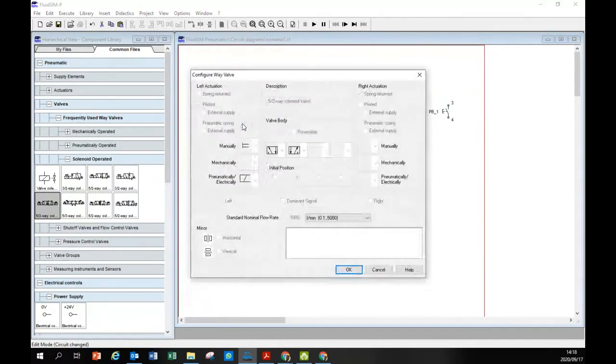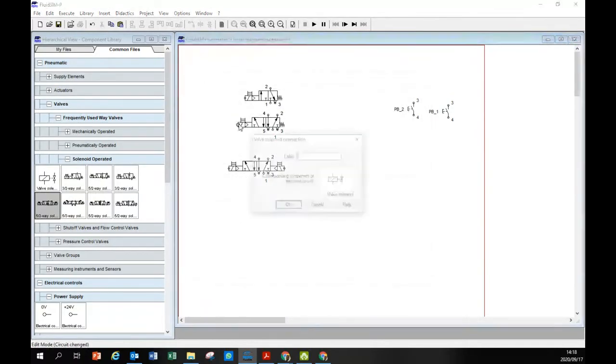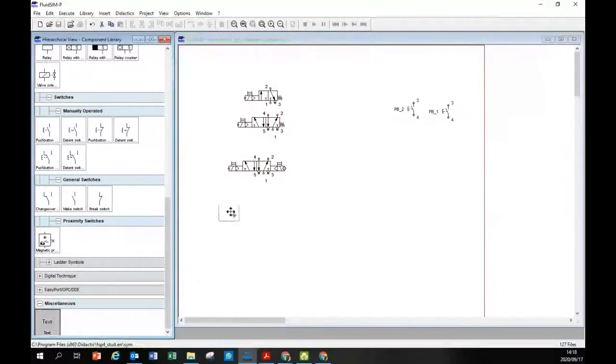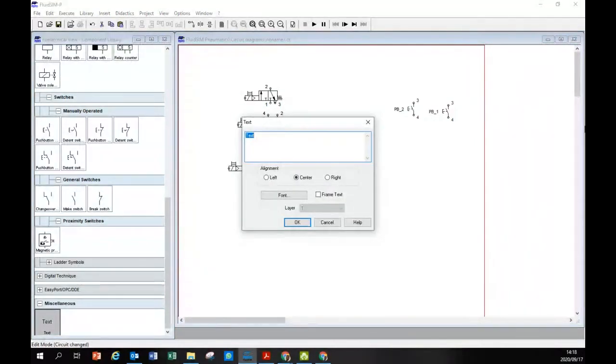We actuate it there. That's right, because you can label once. Can you label this side? You can't. You can label once this side. Can you label the other side? You can't. This one, you can label on both sides. That's why it's a double pilot. Double pilot. Obviously, solenoid. Okay? Solenoid.